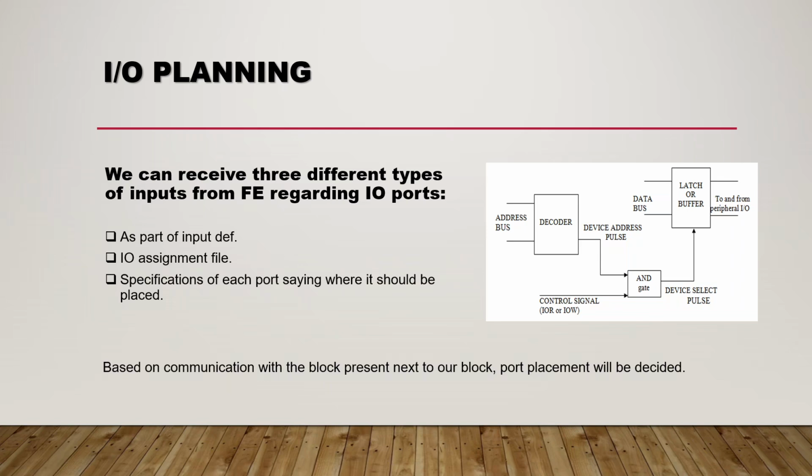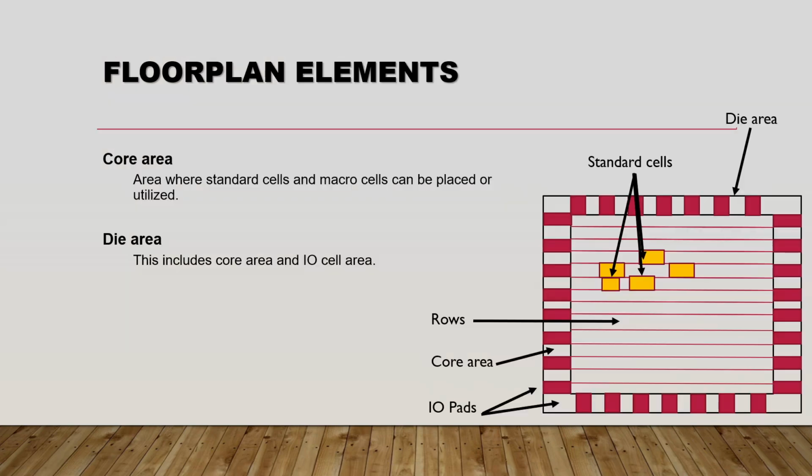Okay, back end thing. Floor planning elements, you need to take care of core area. Core area means whatever the standard cells. Standard cells means, suppose standard cells are available in terms of gates and muxes, or if it is sequential circuits, it is available in terms of flip-flops.